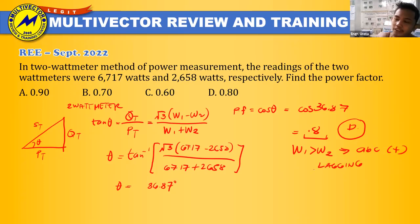Vice versa, if wattmeter reading 1 is less than W2, it is leading. This is under the assumption of positive sequence where the common node is C. So that is problem number 24. Next, problem number 25.